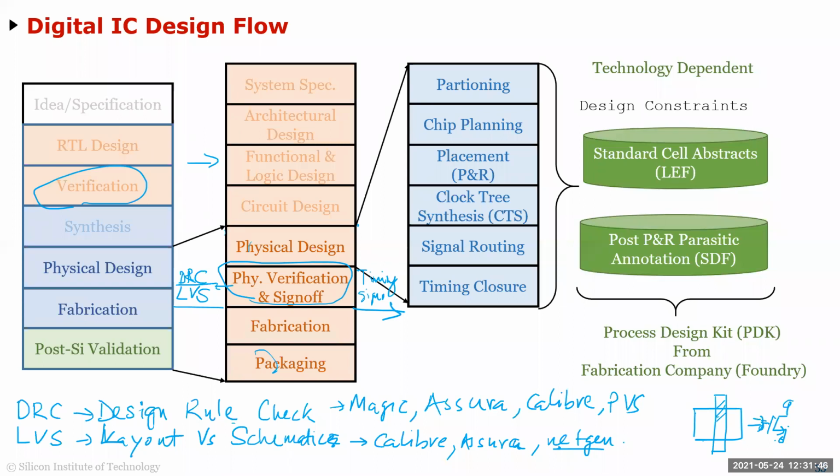It is bounded in the sense that, so let's take an example of an inverter. If you have an inverter and like I gave you an example, after post layout, it turned out that the delay was 150 picosecond. Now they're bounded because of temperature and process. Okay. So yeah, like max and min delay. So you have a max and a min delay.